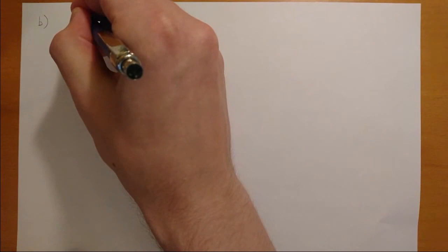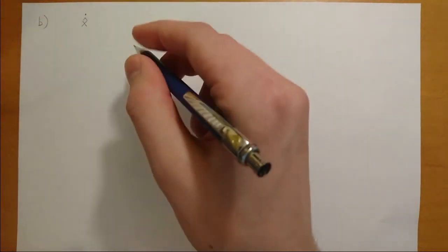And in task B, we're given that, suppose that only the output is measured. Calculate an observer that makes the transfer function from the reference signal to the output the same as in A. Discuss the influence of the poles of the observer. Okay, so we can't measure the states, so we need to estimate them. And then we're using an observer, so that's why we denote with this x hat.